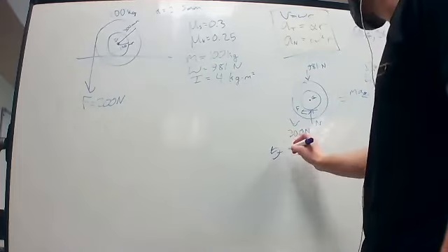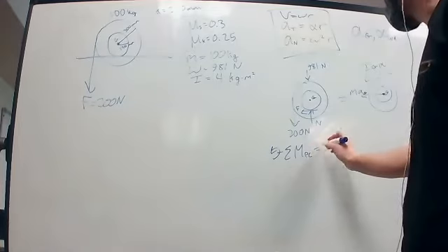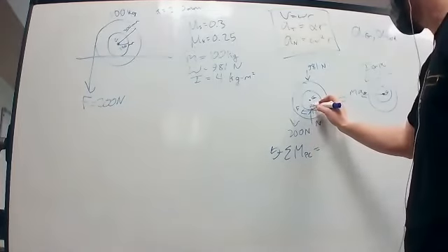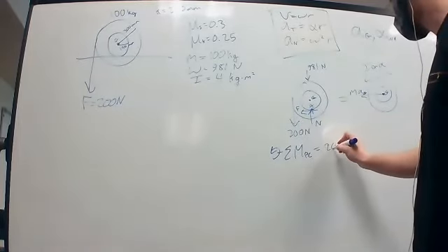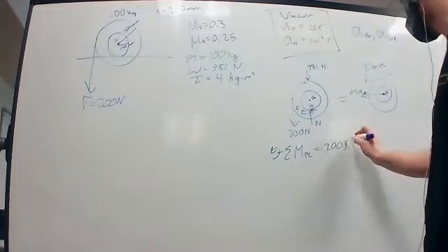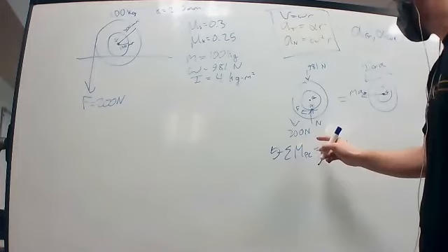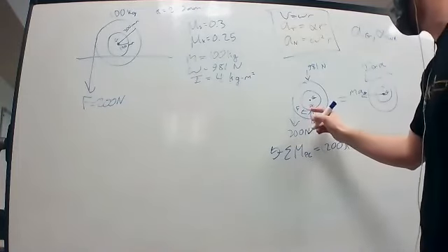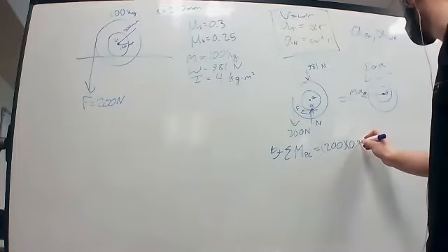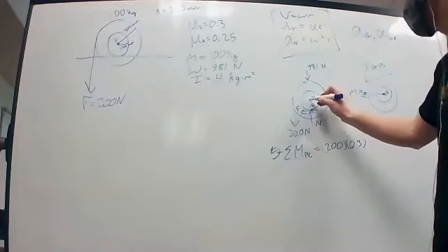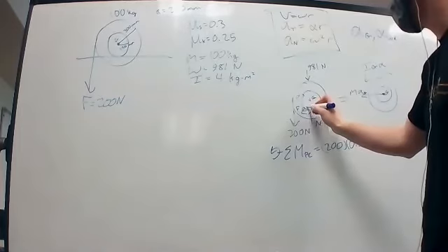So we'll do a counterclockwise moment about the point of contact here, PC. So that's going to be equal to 200 times the distance from, oh wait, it's just this distance. So that would just be the same as the distance from here to here. So it would be 300 millimeters or 0.3 meters, because this distance is 0.3 meters. Therefore, this distance is also 0.3 meters.